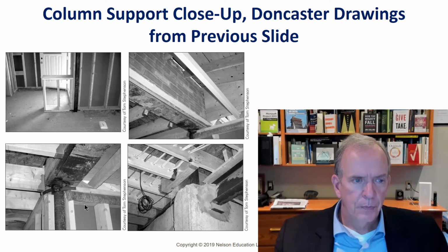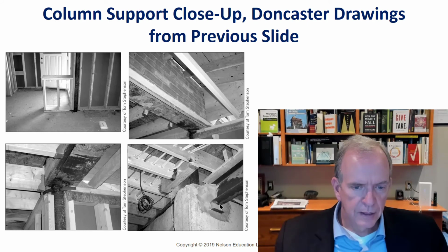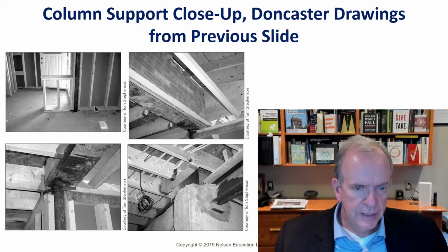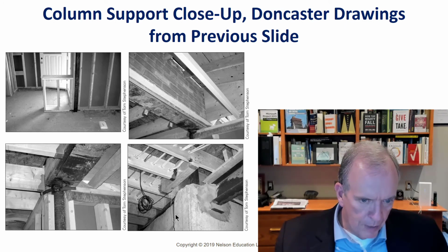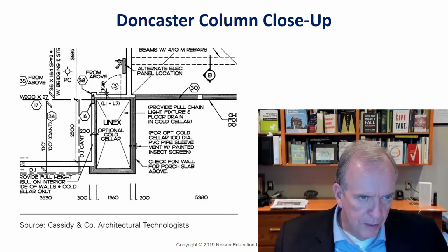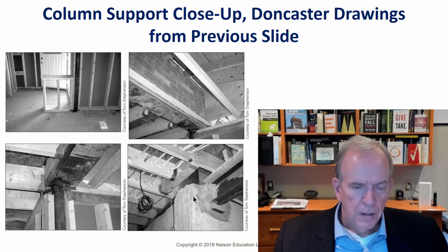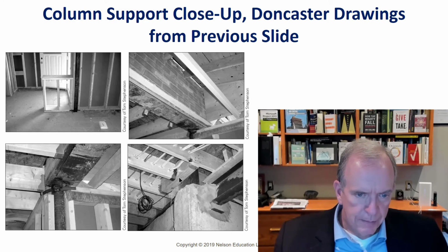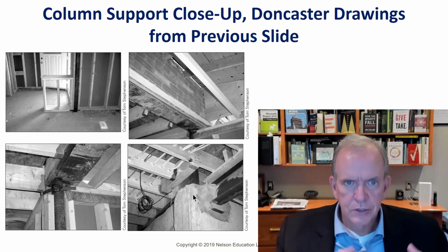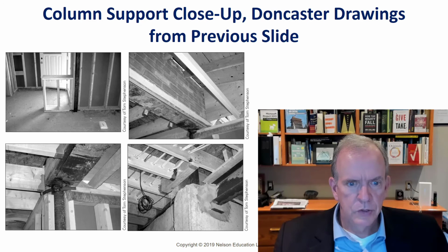So what does that look like? Well, in the basement, that right here is this right there. So you're standing over here looking this way, and you can see how that little corner is out. It's not a straight corner. It sticks out just like here. It sticks out 100 millimeters. There's the size. We have the column that comes down. We had to frame around that steel column so the steel column can come down and sit on concrete, because if it's carrying brick, it has to be supported on a solid surface like concrete. So it can't just sit on wood if it's supporting brick.